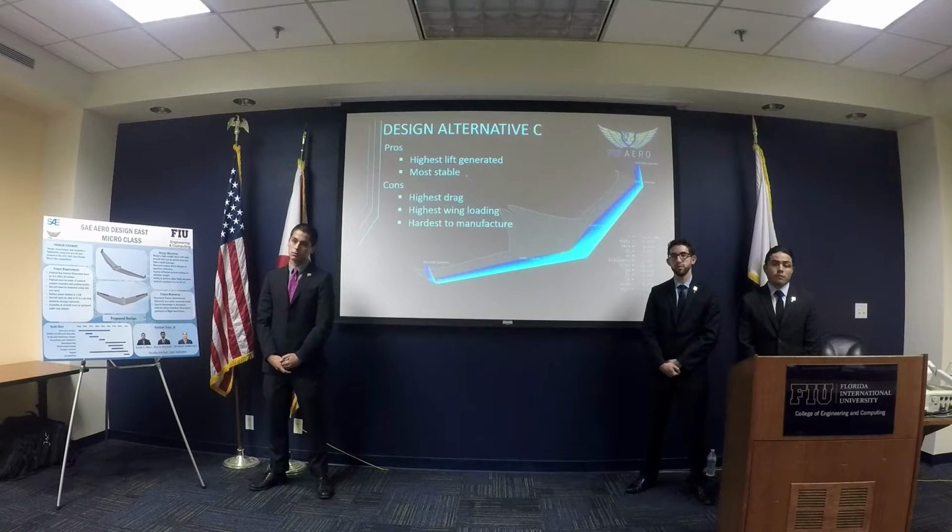Part of your analysis, you have a high wingspan under pressure load. You need to run flutter testing. Your wings are going to start fluttering at a certain condition, and you might just clap. So you need to consider that as well. And my last point is, you mentioned balsa, but at the same time, your design is supposed to be packed into a tube. Balsa is very fragile. How are you going to manage to pack and unpack this thing, or unroll this thing, without potentially damaging the balsa structure?